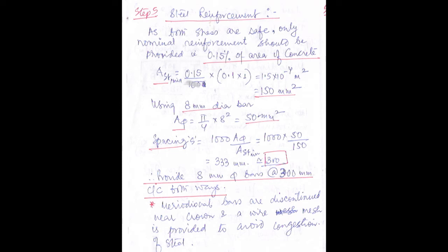As you can see in my video, everywhere the decision we are taking about the dimension, about the steel reinforcement, I am just underlining it. Why am I underlining it? Because while we draw the final diagram, we don't have to search for the data that we have worked out. So please underline the value if you have reached a conclusion or a result.